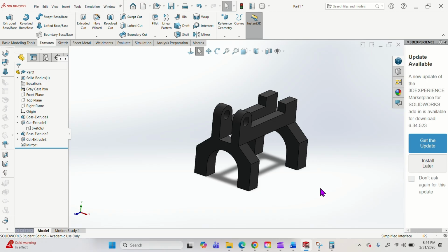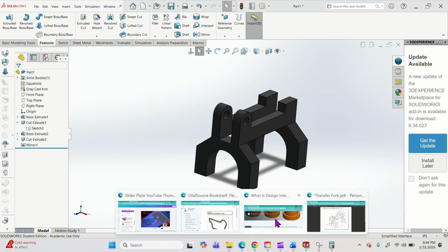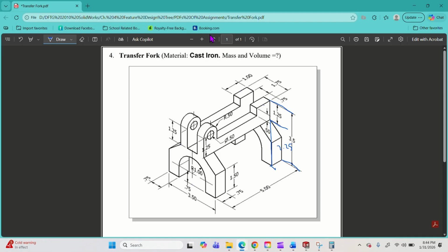And that's also what I was talking about was creating the PDF for yourself. So that way, let me delete this. So when you go through and say you look at your front sketch, you're going to highlight every single dimension to make sure you captured those dimensions in your sketches. And if for some reason you missed one, you're going to fix it, right?